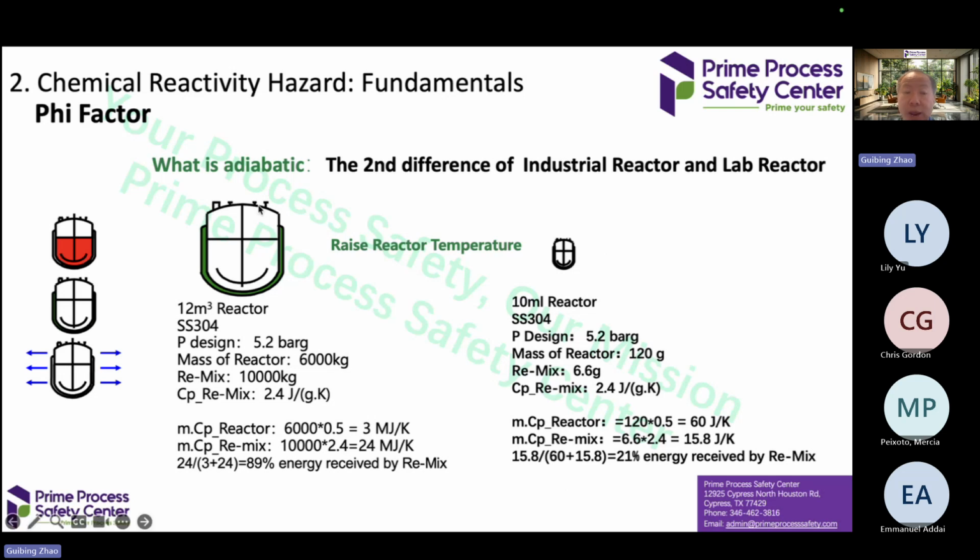However, for an industrial reactor, when you scale the reactor from small to big, you will see a far larger temperature rise than in a small scale reactor because most of the energy contributes to increased temperature of the reaction mixture. As everybody knows, for a reaction, the reaction rate is exponentially increased by temperature.